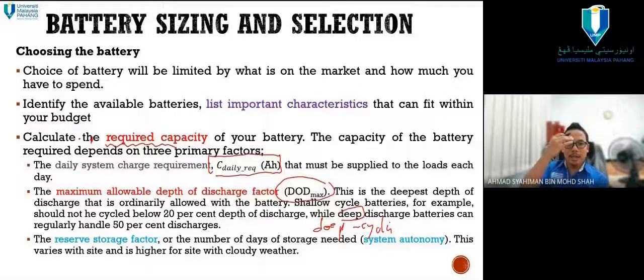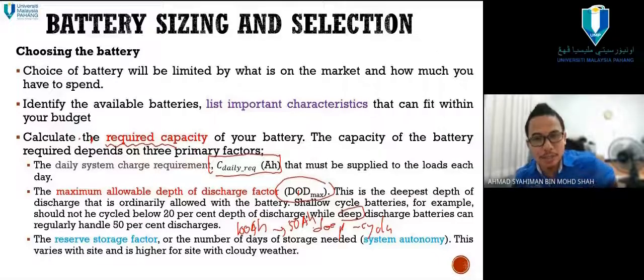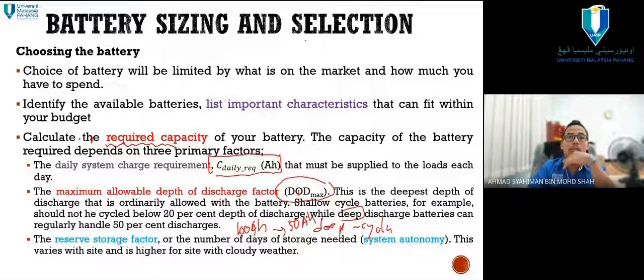Okay. In other words, if we say 50% of the discharge, to make it easy to understand, 100 AH of battery, you use deep cycles. Actually, it's not 100 AH, it's actually only half. Because 50% consider, it's actually we can consider only 50 AH. For the deep cycle lead acid battery, typical case, 50 to 60, I think 50. Actually half of the AH that you see on the outside.